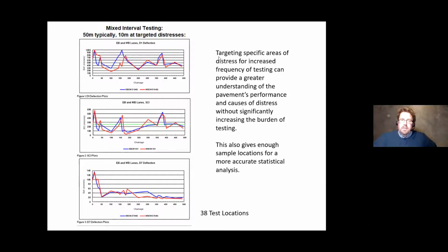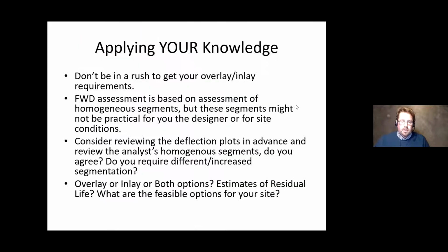So as it says here, if you can target specific areas of distress for increased frequency testing, you can provide a much better understanding, and you get much better value for money out of your FWD test, and you won't have to go back and try and figure out, okay, well, my FWD has come back saying I have no structural overlay requirement, even though I'm seeing these zones of frequency of distress. You can figure out why.